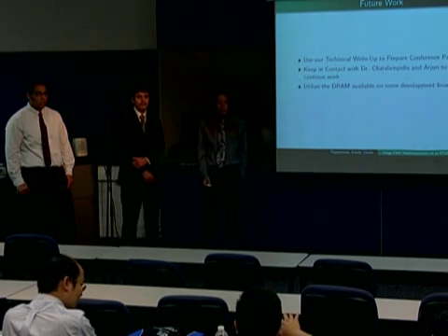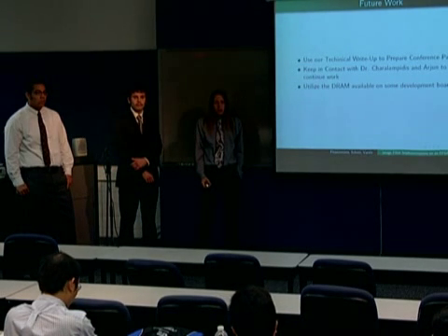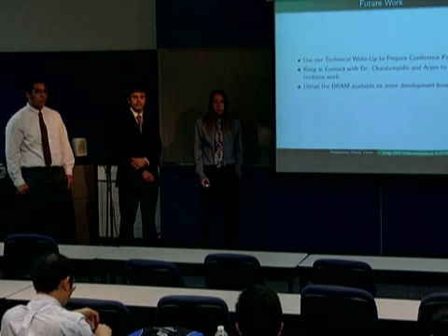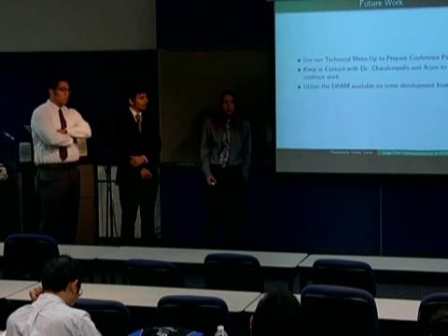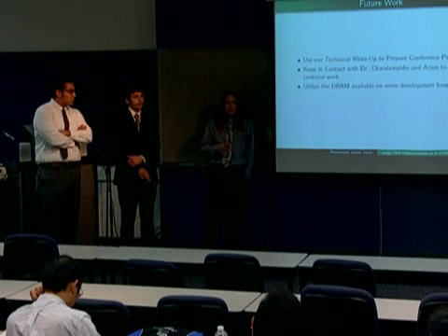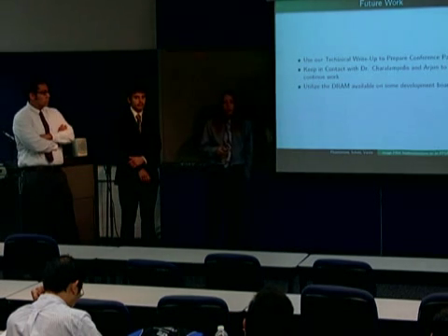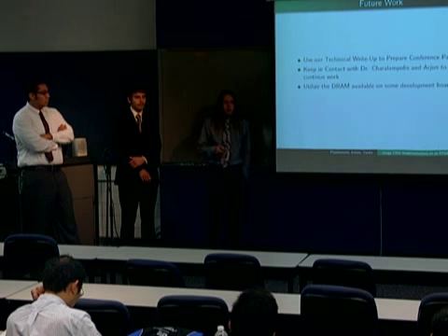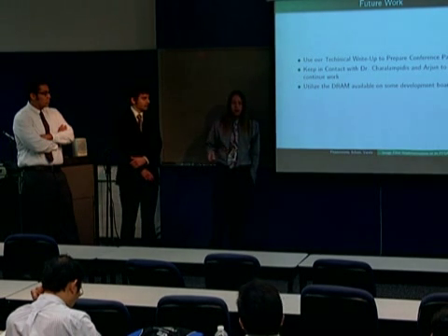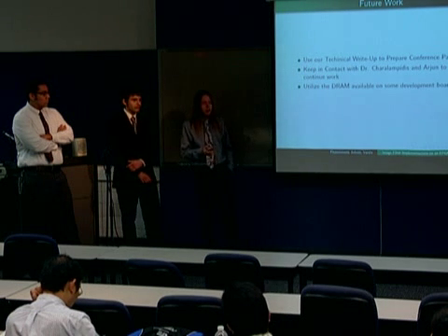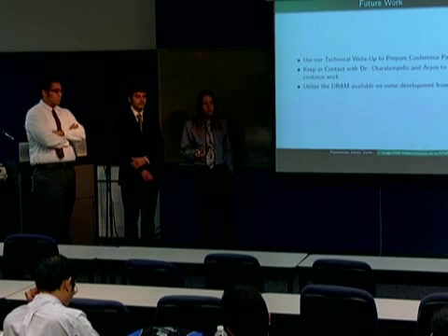I don't know if I understand very well, but you said that you can use either multipliers or lookup tables. So what's the trade-off between using multipliers or lookup tables? Well, basically on an FPGA, or at least the one we use, we have 20 multipliers and 20 BRAMs. And the BRAMs can store data and can be read and written, and multipliers can perform multiplication operations. They're basically blocks of logic specifically optimized and allocated for that purpose.